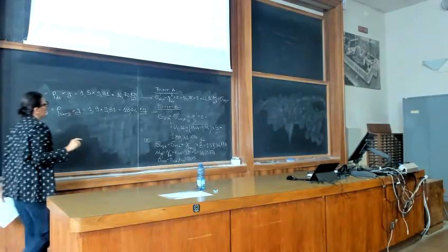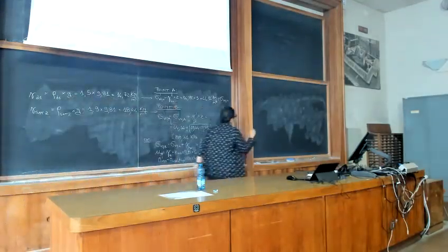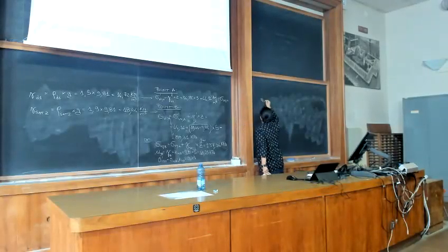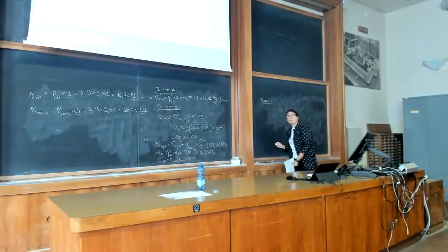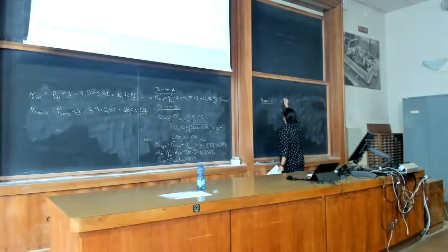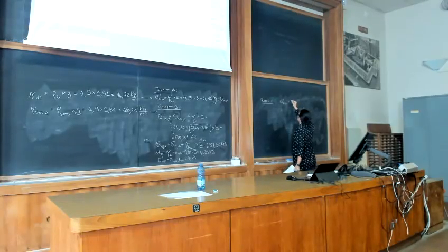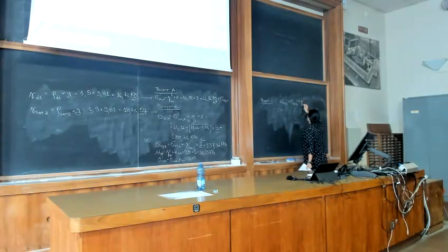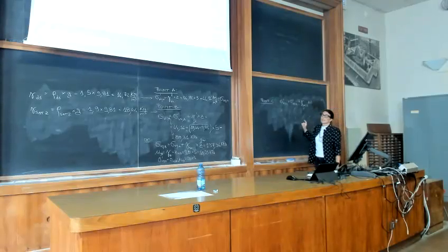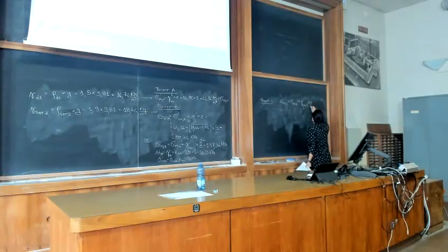So in point C, you can adopt the same procedure and obtain sigma dash V naught in point C equal to sigma dash V naught in point B plus the saturated unit weight of your deposit for the third layer, which multiplies Z. This Z in this case is 8 meters.